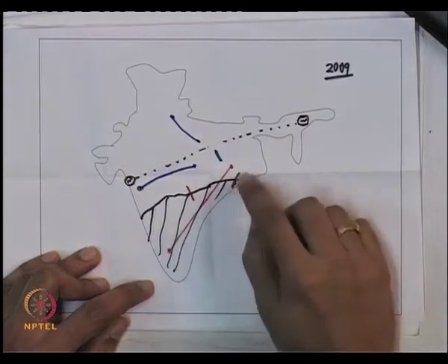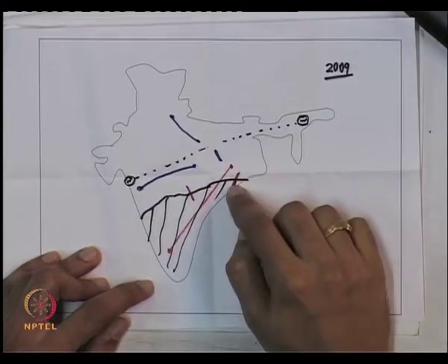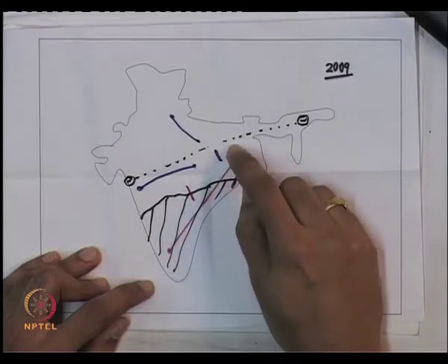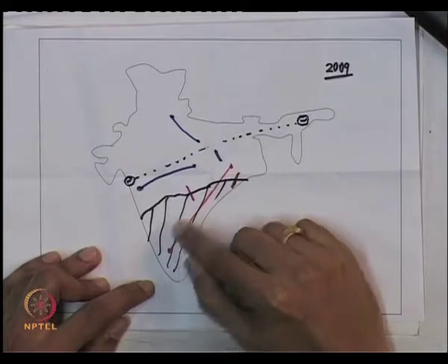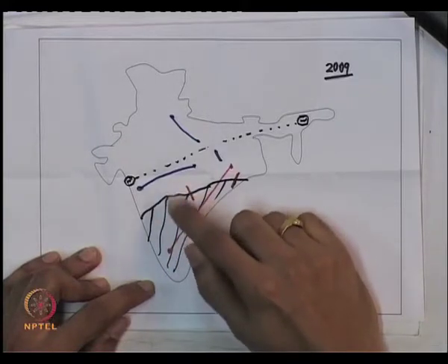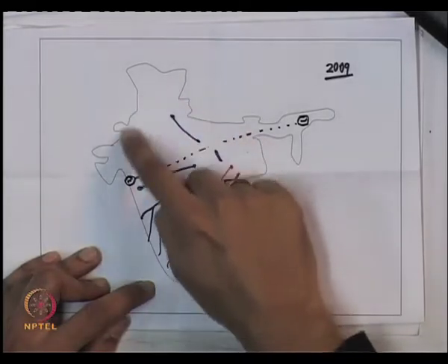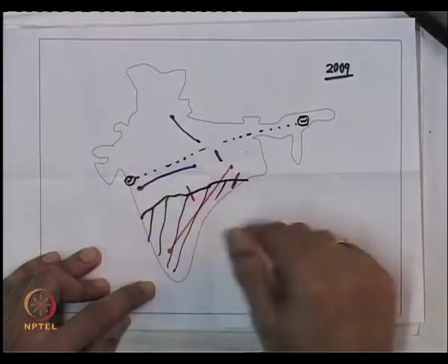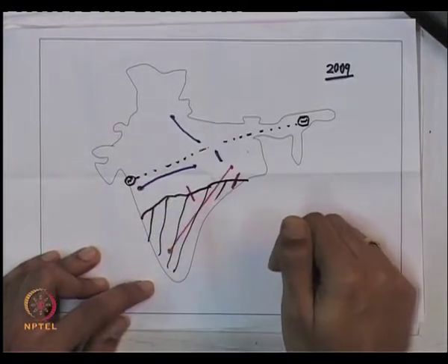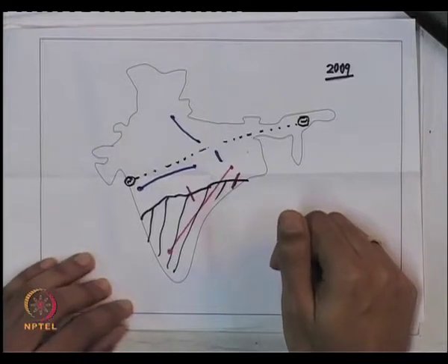However, these are links with controlled power flow. The power flow on these DC links does not depend on the phase angle here and here. That is an important thing about the interconnects between these two regions. In this region, you have a lot of AC lines, in which power flow of course is a function of the phase angular differences of the voltages at the two ends of the line. Now, just to illustrate the fact that we have the same frequency prevailing all throughout a synchronous grid at a given time, I shall just show you a snapshot of the frequencies reported on the websites of the load dispatch centers at various locations within the country.